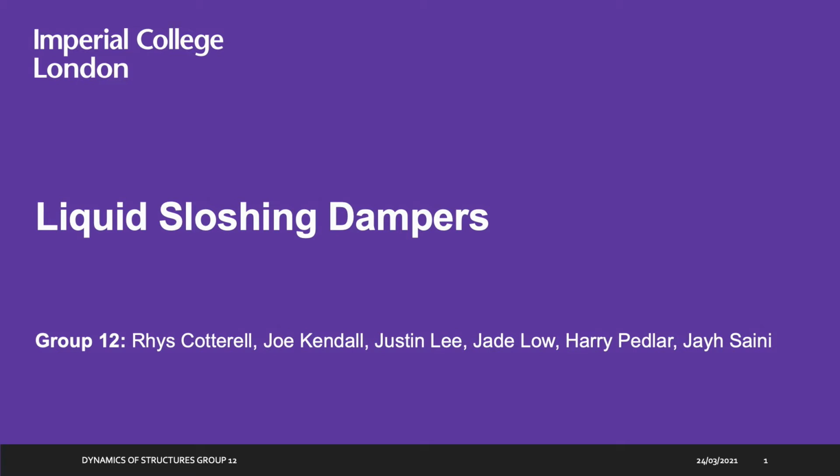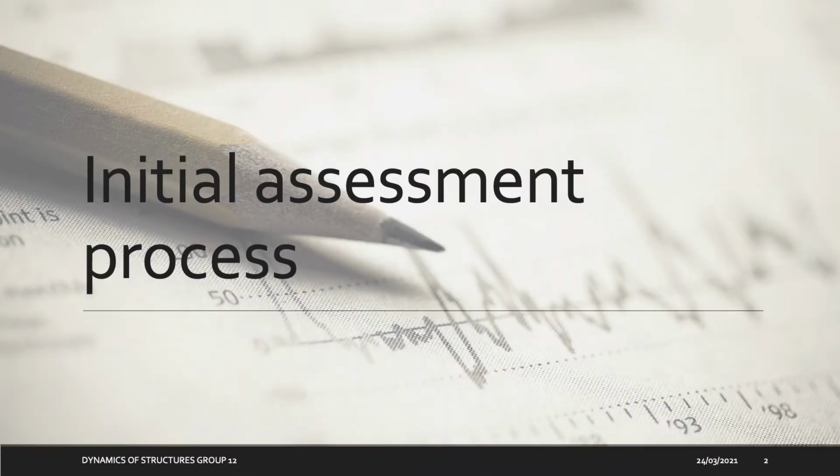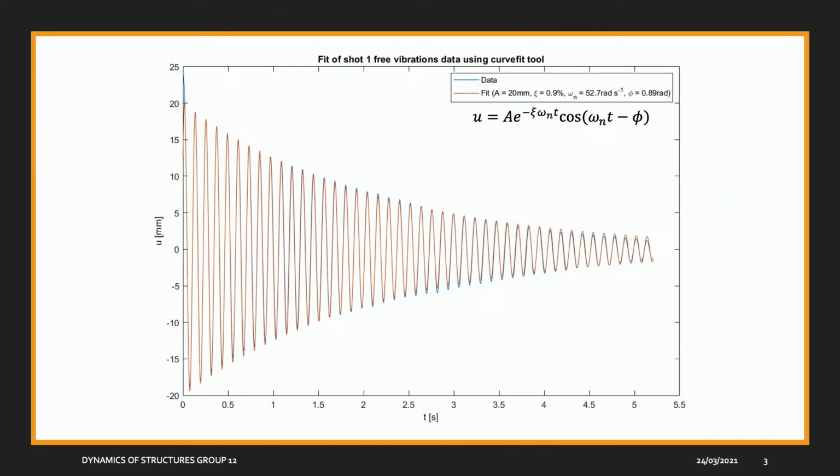In this video, we are going to discuss the modeling of liquid sloshing dampers. The video of the free vibration test was processed in Tracker to obtain the time displacement data. This was then imported into MATLAB and fitted to the exponentially decaying sinusoidal curve shown here using both the MATLAB curve toolbox and by manually calculating logarithmic decrements. This gave the system's original damping ratio and natural frequency as shown here.